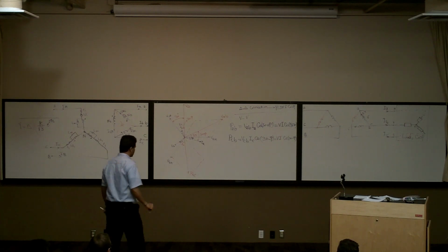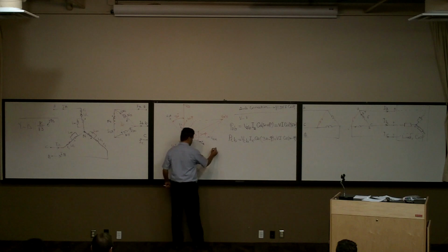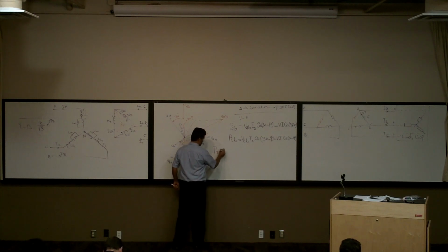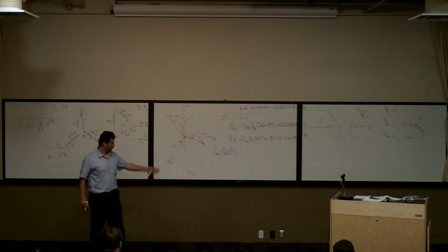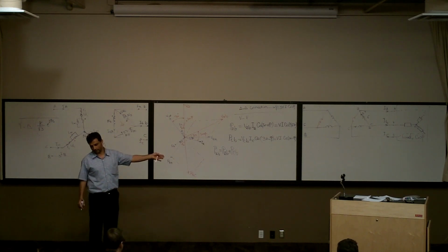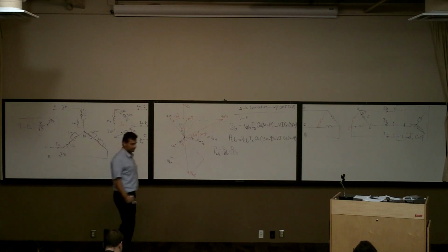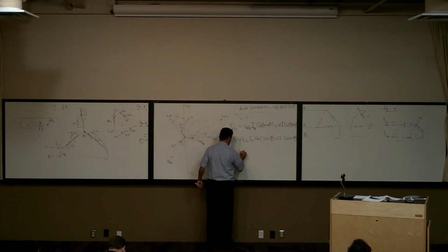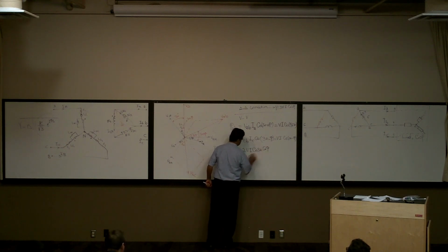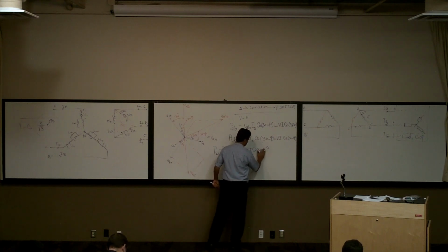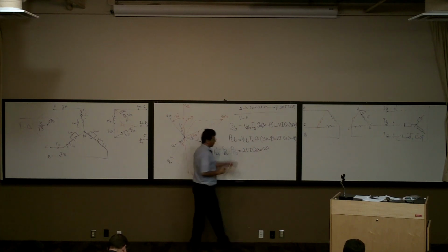Okay. So how much is the P in total now? It's going to be PAB plus PCB, right? Let's call it PVB. How much is the PVB in this case? It's going to be PAB plus PCB. If we calculate this one, it's going to be 2 VI cosine 30 cosine phi. Just add this together.